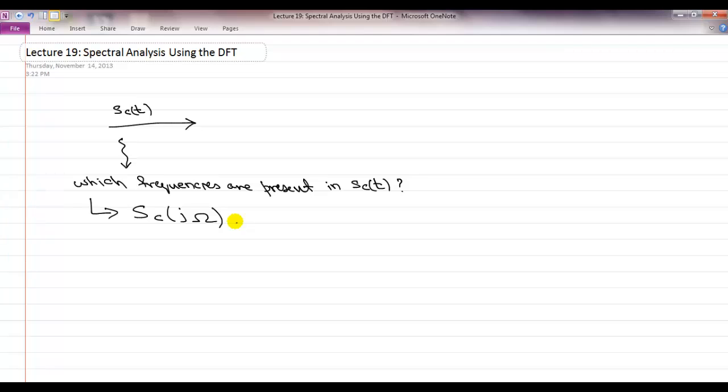When you don't really know whether your signal has a particular form, what is the first principle of sampling? You put an anti-aliasing filter in front of that signal. So you have a hypothesis that the signal you're interested in ranges from this frequency to that frequency. Based upon that, you design an appropriate anti-aliasing filter.